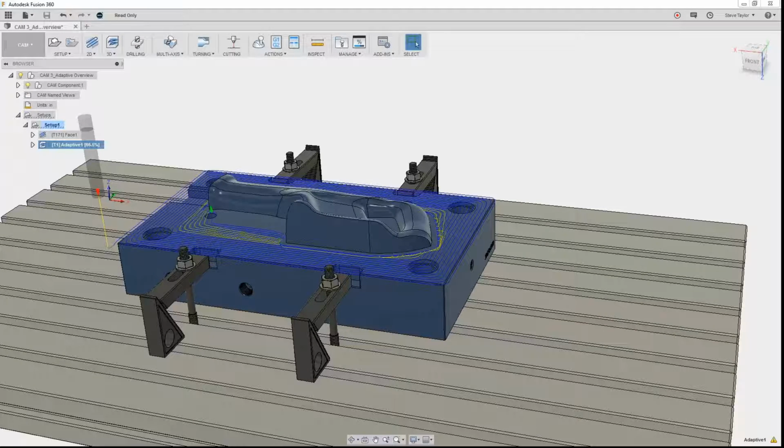Because this tool can come down as low as it does, you can see the tool path actually starts by clearing most of the geometry on the first level. Then it will start working its way up the part. The long yellow sections show the full retract that we have between transitions. You also have the option of not having to fully retract, which we'll take a look at for finishing.